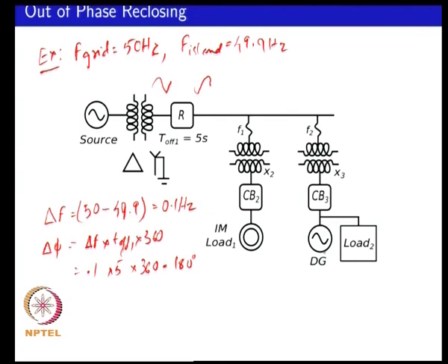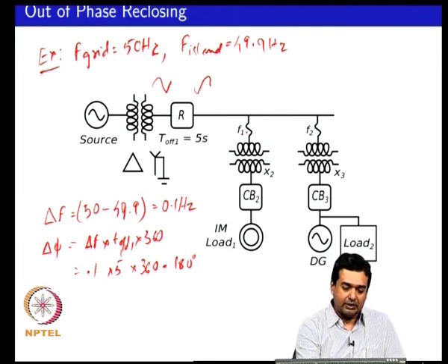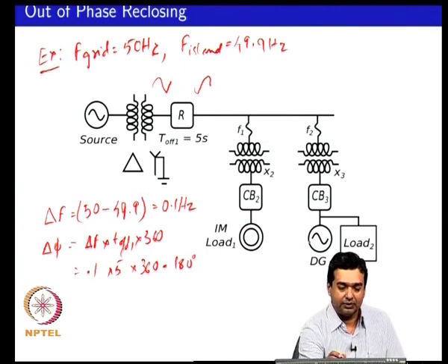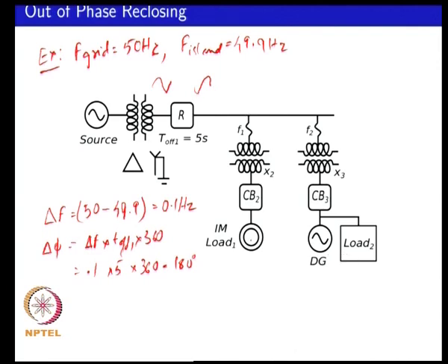If this is a synchronous machine, then you could potentially damage the DG source. If there are fuses on the distribution system, the current that it might draw might be large enough to open the fuses. And what we will see is that if you have a neighboring load, when the voltage over here drifted for 5 seconds and became out of phase, then essentially the phase of the flux vector in your machine is also following that particular voltage in the island.